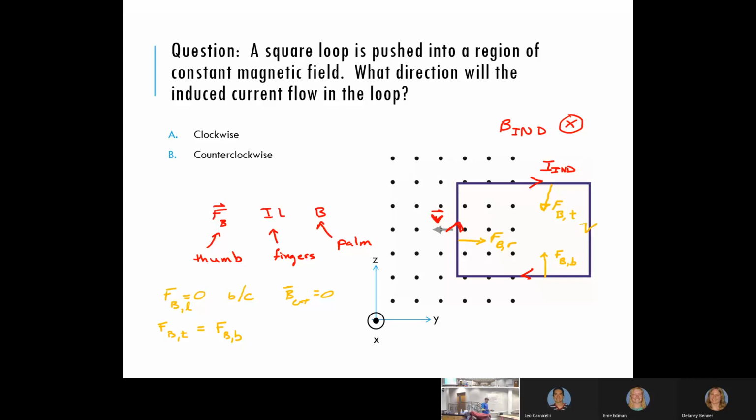If you let it go long enough, you start gouging the rotor, and now, instead of doing a $60 brake pad change out, you've got to do a $150 rotor and brake pad change out. And oh, by the way, when you change your rotors, you got to do both sides. So if you damage the rotor on one side, you got to change the one on the other. So now you're up to 300 plus labor, et cetera. It's a mechanical contact. Sorry, it's not like I haven't done that. And if it's really bad, you get a seized caliper.